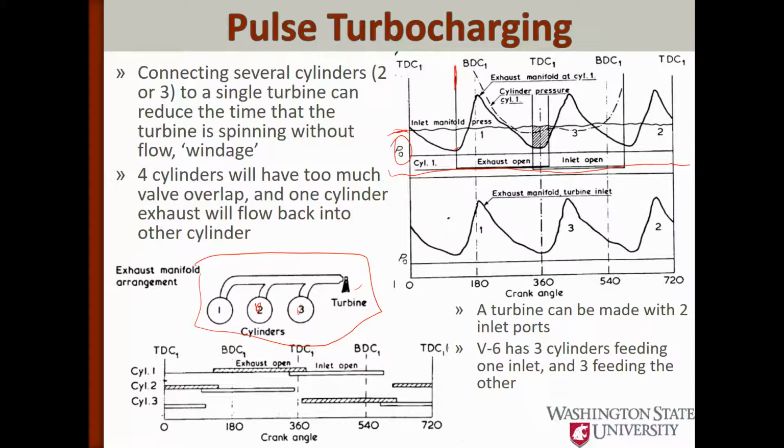And as soon as that exhaust valve opens, the pressure between the cylinder and the turbine rises very quickly, and then it spins up the turbine and it flows through the turbine, and then the cylinder starts exhausting less and less, so the pressure starts dropping, and it's going to keep dropping closer to atmospheric because remember it's venting to this atmospheric pressure.